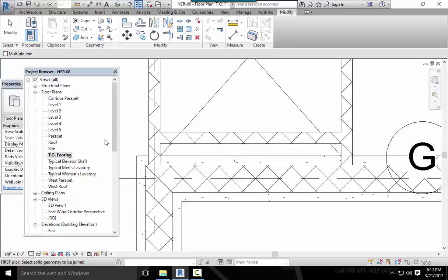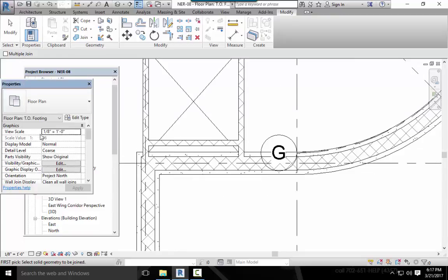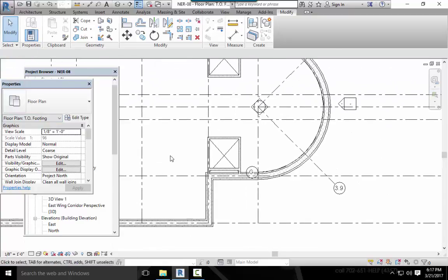All right, structural slabs. Structural slabs are basically thick floors. The one you're about to use is a solid concrete floor 12 inches thick. Of course, Revit doesn't have something this thick built in the library, so you'll take this opportunity to make one. Here are the steps. Go to the top of footing floor plan. We happen to be in the top of footing floor plan. Zoom into the elevator area.